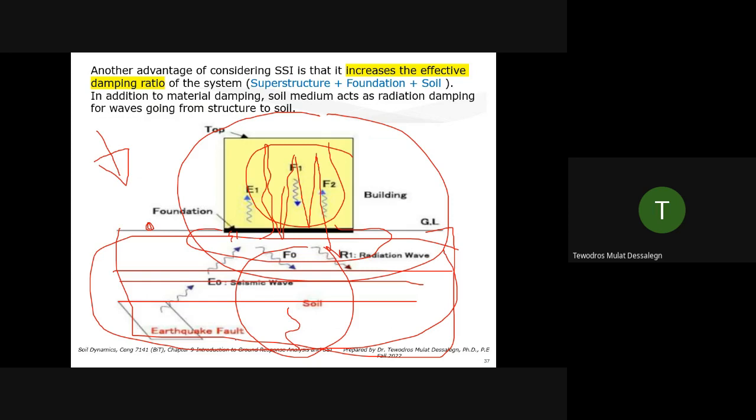Because when you do the wave propagation through the soil, the impact of the structure will affect how much output you'll get at the ground surface. So the NRC usually forces us to do it together. Everything together, the soil and the structure together. So that's how it is commonly done for critical structures.